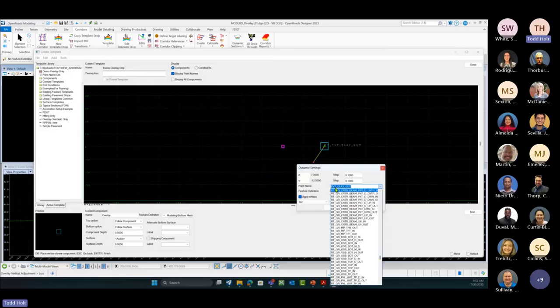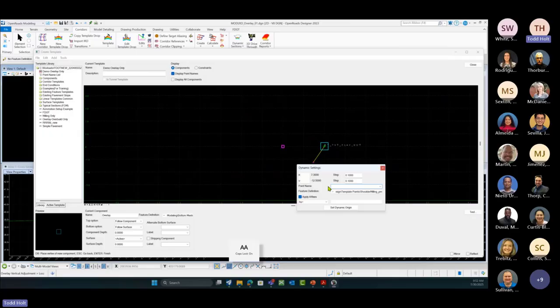We'll just keep it the point name for there, or if there is a null point. I forget the point names on there. We want to use, so we'll just keep it the pavement overlay layout for right now. We'll come back and change that, or we could change this in the point names. So let's just rename that to, I'm gonna hit my caps lock, we'll rename that to CL.